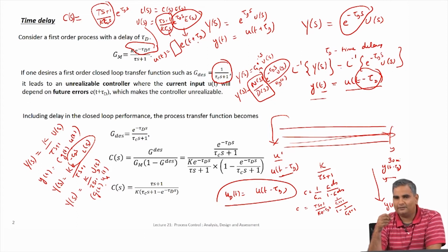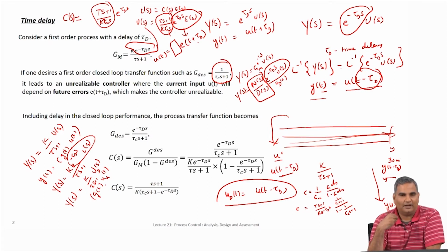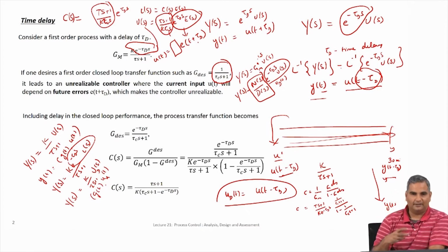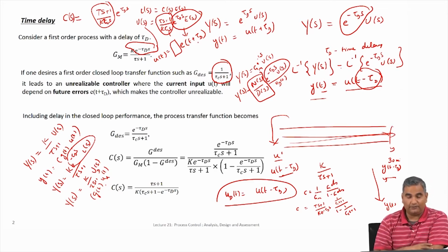So you see why this time delay creates problems in control, because you have taken an action and you really do not know how long you have to wait, because you cannot get a very good estimate of the time delay at all times, right. So you just have to wait, and you do not know whether it is that you have not opened the knob enough, because of which the water has not become hot, or whether it is because of time delay: you have opened the knob enough and if you wait for long enough, you will get hot water. So it is a very interesting question, and it makes the controller design that much more complicated, particularly if you do not have a very good idea of how long the delay is and so on.